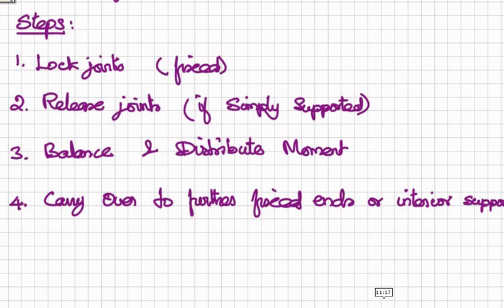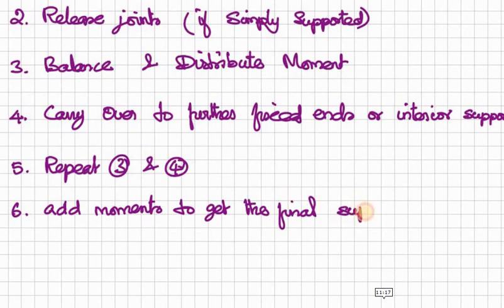Once the iteration is just enough, we can add up all the columns under each joint to get the final support moment. For sway analysis of portal frames, shear equations shall be applied.